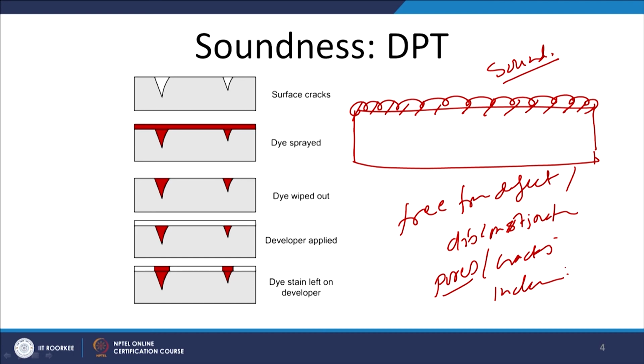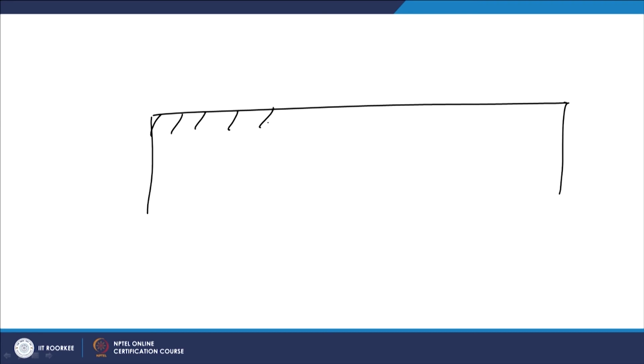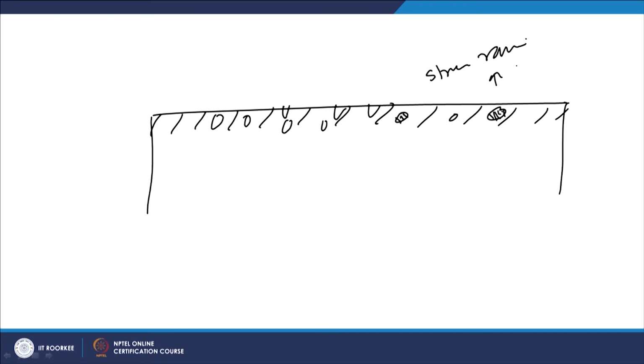So, this will not lead to a good situation, because if the defective modified layer has defects in the form of cracks here and there, pores in the modified zone, or inclusions of foreign material or impurities, then these will act as stress raisers, increasing the stress concentration.